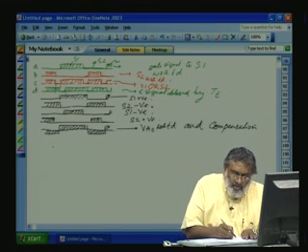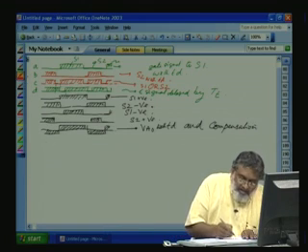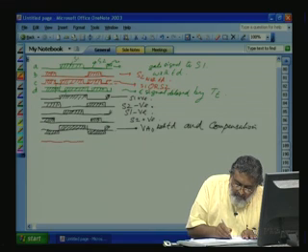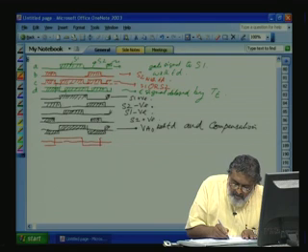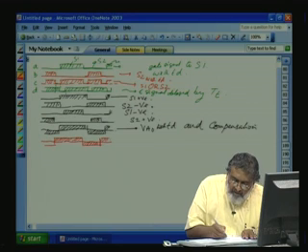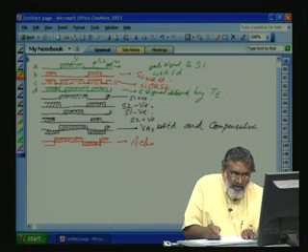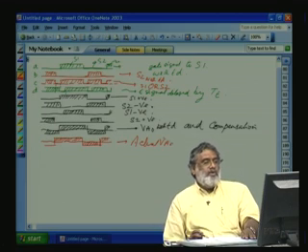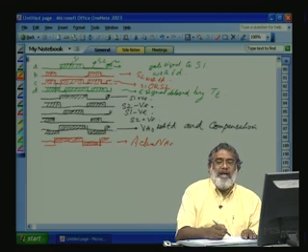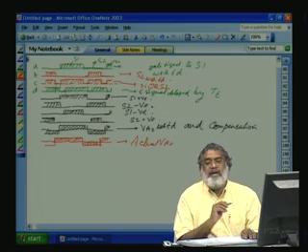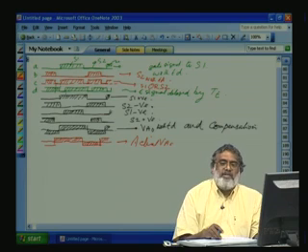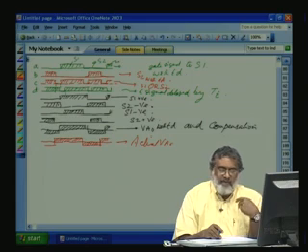And the actual signal without compensation, what we require, is like this. So the actual VS0 and the compensated VS0, the positive and negative areas are the same, but the waveform is slightly delayed by TD. That's okay. TD for a switching device is around a few microseconds, so for motor drive applications this delay is negligible.